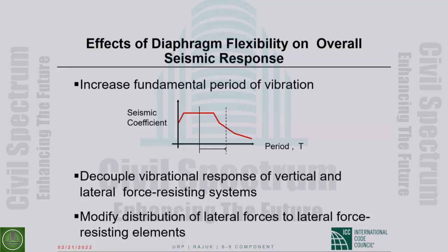But the diaphragm, if it is flexible, will increase that period. And as the period increases, the initial period may have been here on the design spectrum. So this is our design force. The elongated period may be here. The design force has come down very significantly.